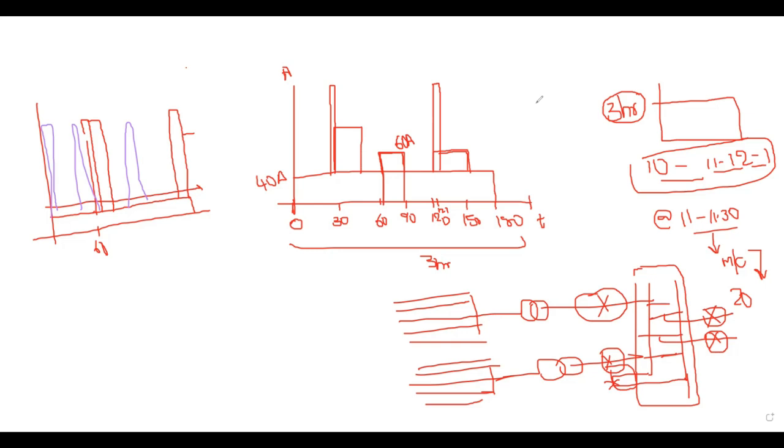It's a general thing, right? You're allowing the voltage variation plus or minus 10%. If it is plus 10%, 220 plus 10% is 242. The battery is supposed to feed that 242 volts. If so, 242 divided by 2 volts per cell comes to 112 cells.